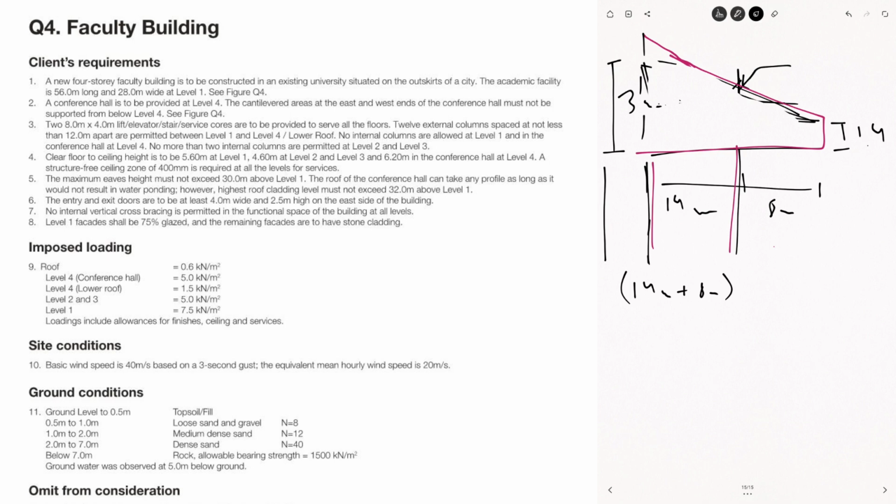I got all the information right now and the moment and everything for the point of the cantilever of my truss. And what I want to now calculate is what's the height of my truss. I know there's 1.4 here. What's the actual height at this point, which is about 8 meters. Okay, so I'm doing a linear interpolation. It's 14 plus 8.